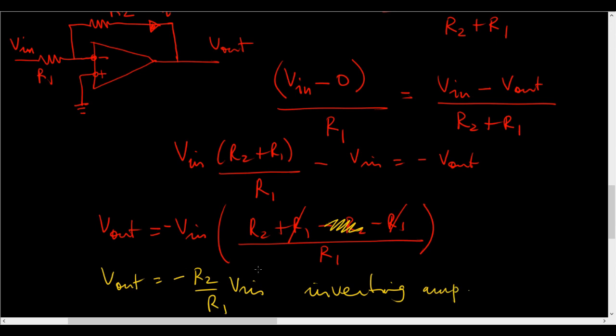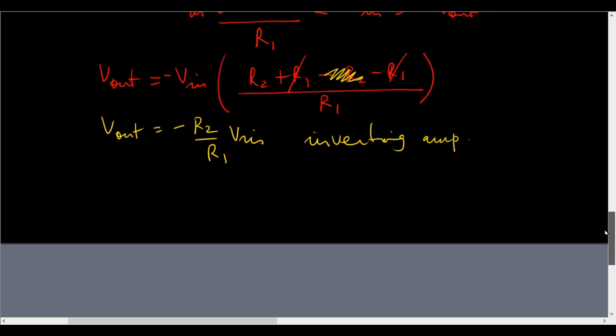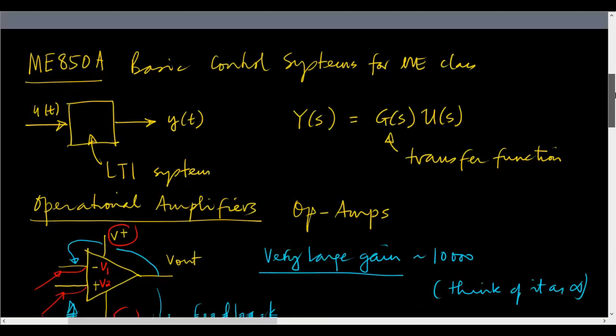Okay, so you can take R2 by R1 to be something like 10 or 20 and it will work. You will get a larger voltage over here at the cost of drawing a small amount of current. Okay, now let me show you something a little more interesting.